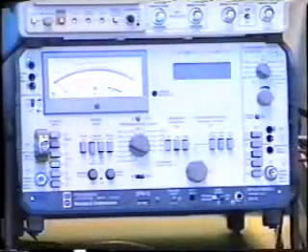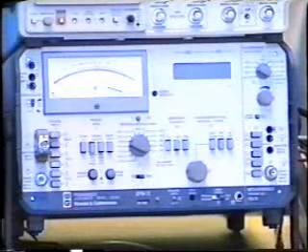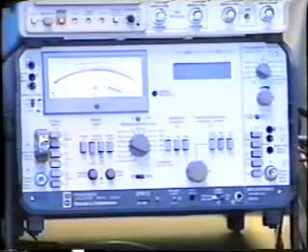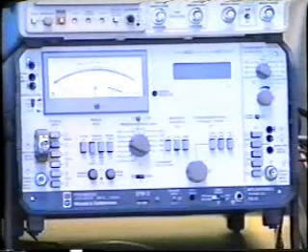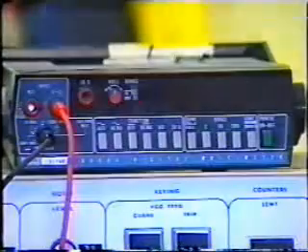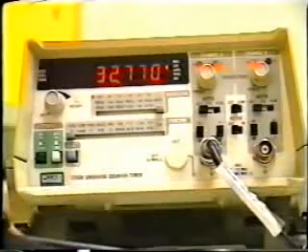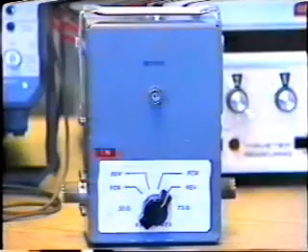You have observed that specific test equipment is required for setting up carrier systems. The essential devices are the frequency selective voltmeter, which registers the signal at the selected frequency only and disregards all other signals, the signal generator to provide a test signal at selected frequency, the RF voltmeter, the frequency counter, and the reflective power meter.